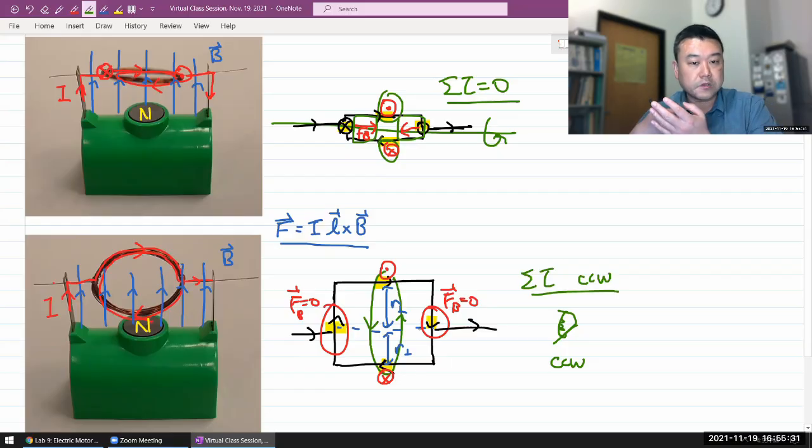So applied over some amount of time, that'll cause the loop to rotate. And that's exactly what you see with this world's simplest motor. Now, I don't remember in the demo if it actually spun in this direction or not. If it actually went the other way, what it would mean is one or the other: it could be that the current was actually flowing the other way. I don't know, I couldn't track the direction of wire in this screenshot. Or it could mean that the direction of the magnet is opposite. Flipping either of them will flip the direction in which the motor runs.